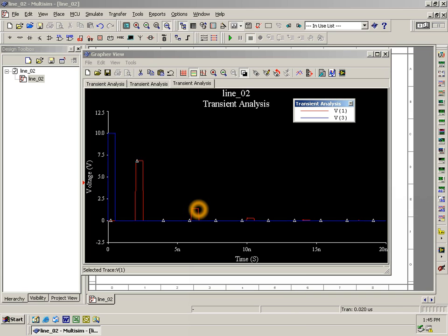And you'll see a couple things. They seem to be spaced out at about 4 nanoseconds. Well, 4 nanoseconds happens to be the time it would take for a reflected wave to be emanated from the load resistor back to the source and then back to the load resistor. So this is the round trip path from the load resistor back to the source through that 2 nanosecond time delay, and then all the way back to the load resistor. So each reflected wave is 4 nanoseconds.